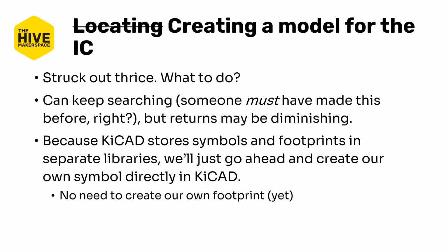So instead, because this is a KiCAD tutorial, we're actually going to go ahead and make the symbol in KiCAD directly, and I'll show you how to do that. Symbols are relatively easy to make and are much less prone to errors than custom footprints, but they can be tedious with many pins. So it's totally acceptable to wait for Ultra Librarian or SnapMagic to generate them, but it's totally doable to make them on your own as well, unlike footprints, which can be a lot more of a pain.